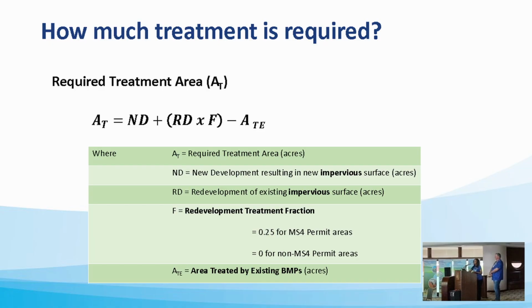This is a program where if you're unable to treat or provide water quality for the impervious area, whether it's new impervious, new development, or your redevelopment, then you can request a variance, and there will be an alternative compliance, meaning DOT will have to put a post-construction BMP somewhere within the same watershed, or they would have to take a different watershed with either equal or higher area.